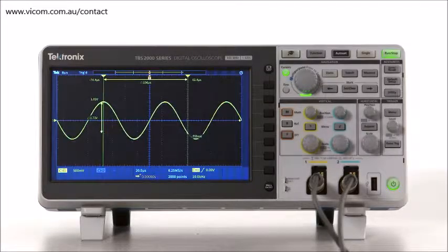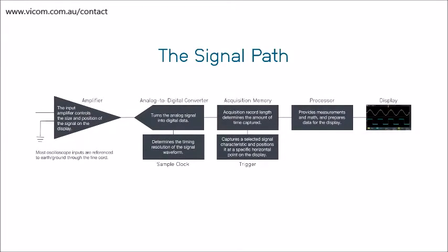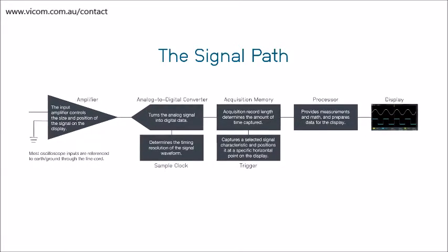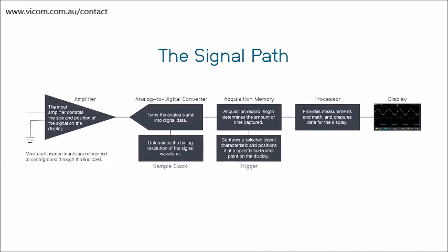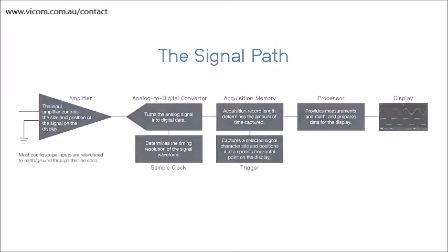In the previous video, we measured time and amplitude characteristics using oscilloscope graticule and cursors. These visual measurement techniques provide great estimates of voltage and time. However, their accuracy is limited by graticule resolution, cursor alignment, and display resolution. Modern digital oscilloscopes provide built-in automated measurement functions that perform measurements on the digital signal data converted by the analog to digital converter in the scope. Since the measurements are performed on digitized signal values, they aren't subject to errors introduced by eye.